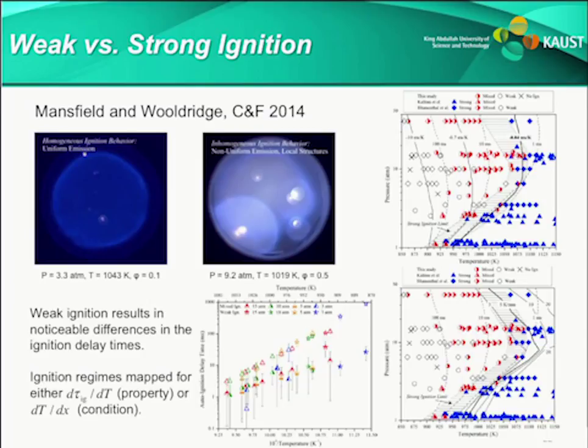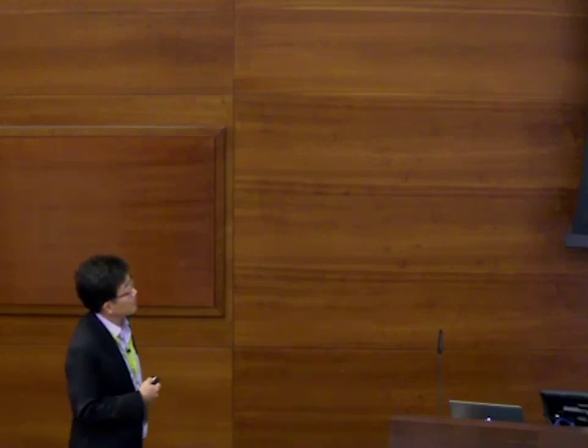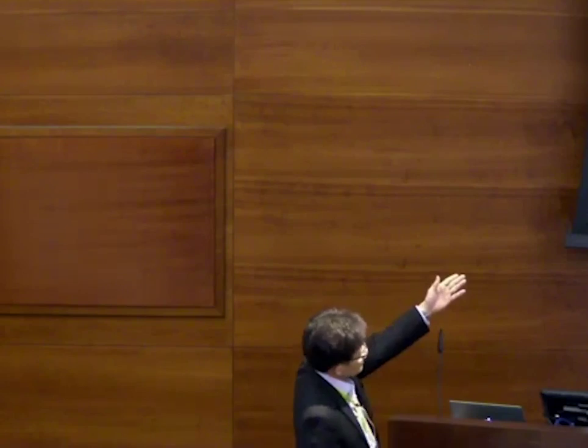And it turned out the boundaries are clearly mapped out as a function of ignition delay time sensitivity to temperature. In fact, the idea of coming up with this kind of criterion was not entirely new. It originally came from an old study back in 1970 by Meyer and Oppenheim. They also found the same thing in the shock tube ignition problem.